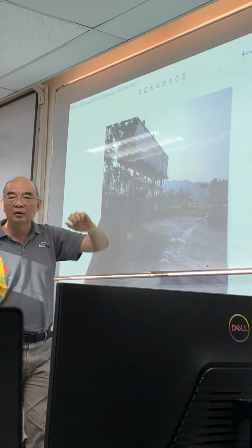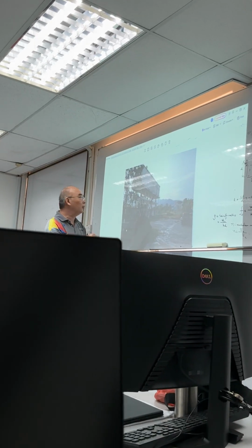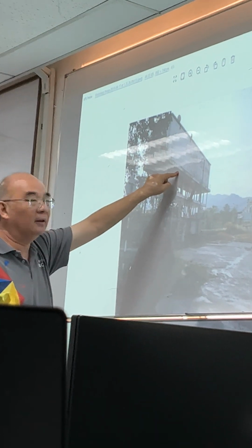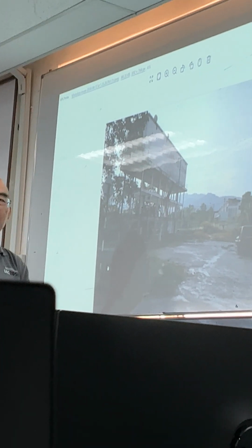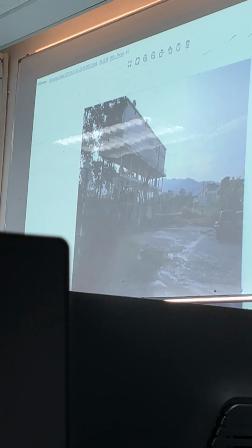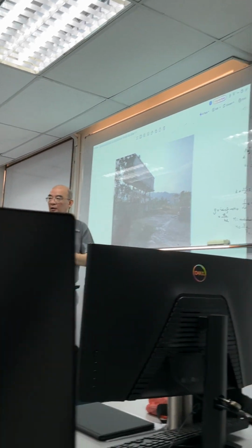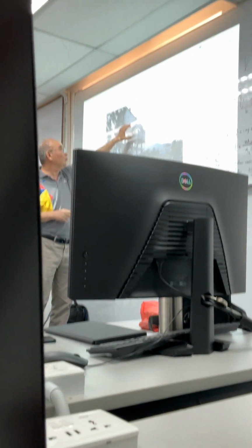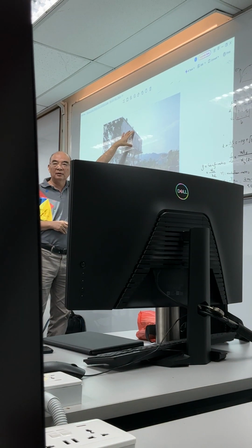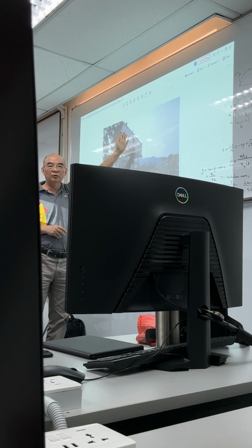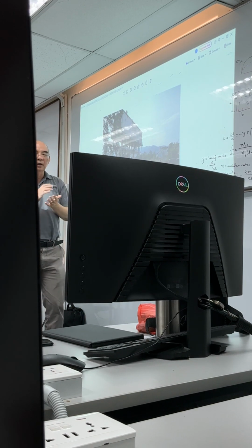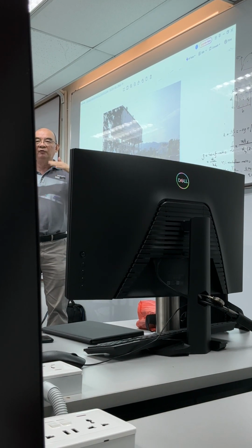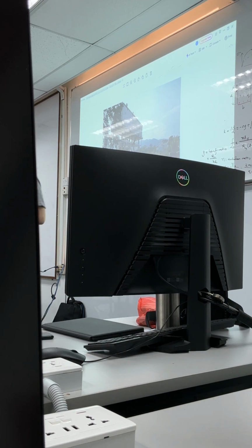Because it's elevated, so you have the columns, right? Okay, so the problem 11.3 is looking at this part, the wall and the slab. When we talk about water retaining structure design, we are more actually looking at this part here. Because here this is the lateral load. This part here is the vertical load, which you have learned how to design the beam and slab for, right?